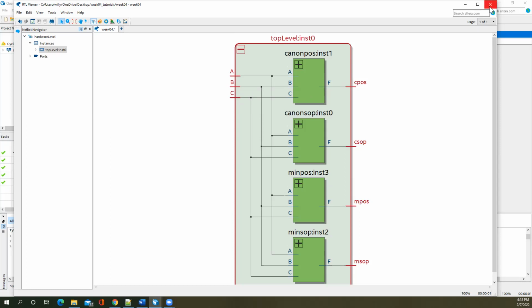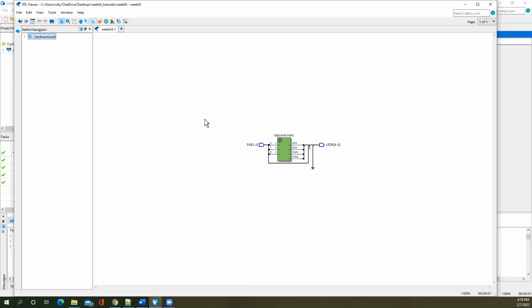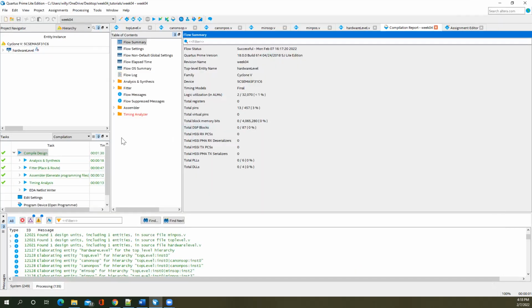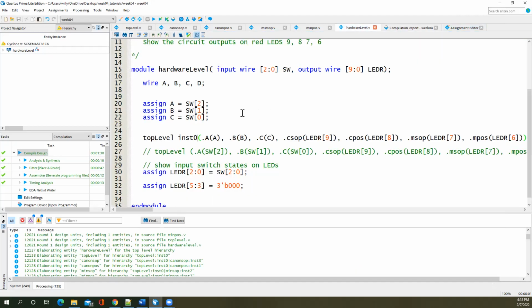So the RTL viewer, right, gives you a good snapshot of what your design looks like, symbolically. And then if you go all the way down to the lowest level circuits, which gates have been used to implement it. All right, that is the end then of this tutorial of using these hardware signals within some of your lab assignments, right, within an instantiation of a module. All right. So I made this for my students in digital logic design lab. Right. Hopefully it's helpful to anybody else that's working with an Altera board as well.